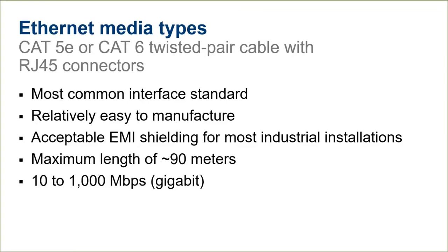So kind of going back to the RS-485, twisting pairs helps reduce the noise, the amount of interference between them. Each of the 4 twisted pairs in a Cat5 cable, on average, has about 6 twists per 5 centimeters approximately. These pairs are typically made from 24-gauge copper wire within the cable itself.